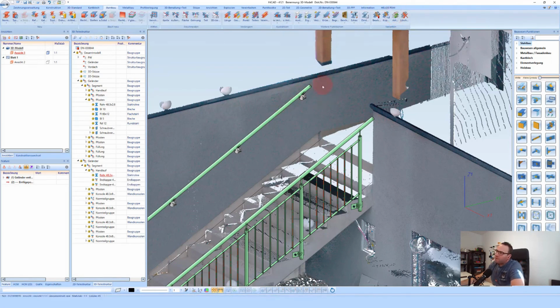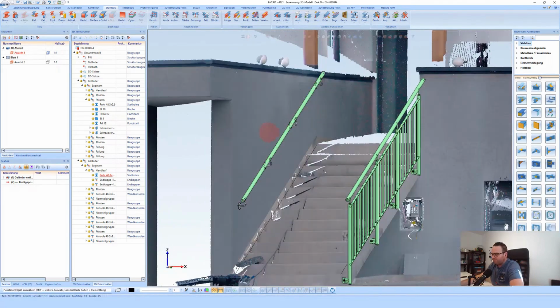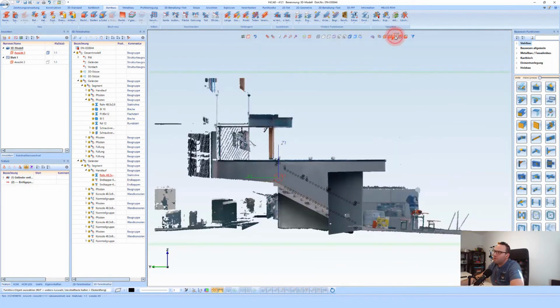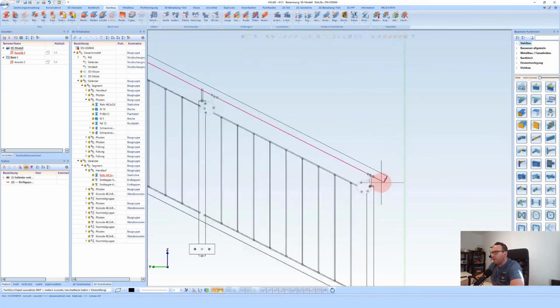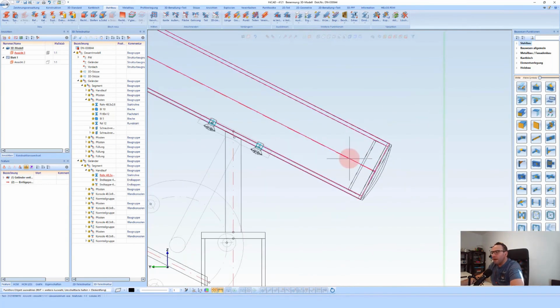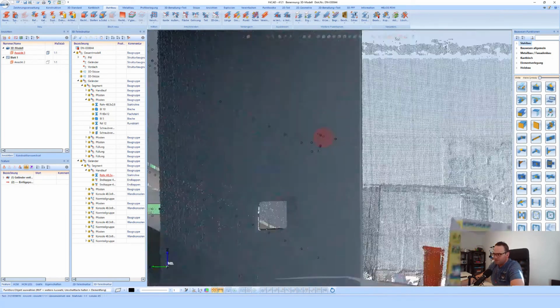And now I can check how this will fit together with the mast in this case. That means, if the wall handrail is in the air or not, how can it still be attached? It would naturally fit here as well. Of course, I can also perform the check here again. I can go ahead and look at a side view, and I am now deliberately switching to the hidden line mode to simply see where these handrail parts are located. They are now, in terms of height, on the same plane, which means it fits, and I will leave it like that.